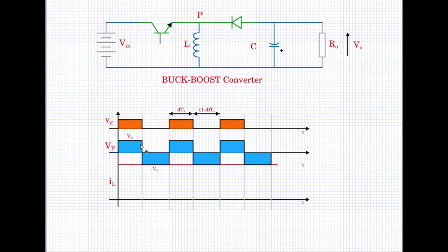So this whole height of this waveform from here to here is V in plus V naught. So you have a V naught and you have a V in. So this Kirchhoff's voltage loop equation, if you apply, that is the amount of voltage that the diode has to withstand. Or look at the pole voltage, the height from this point to this point the diode has to withstand, which is V in plus V naught value.